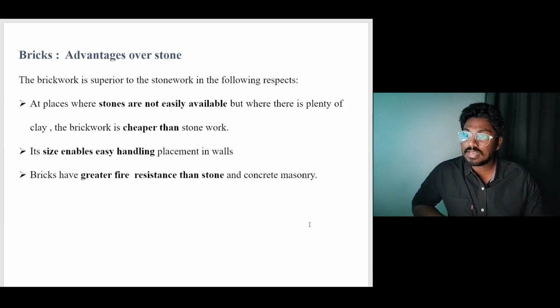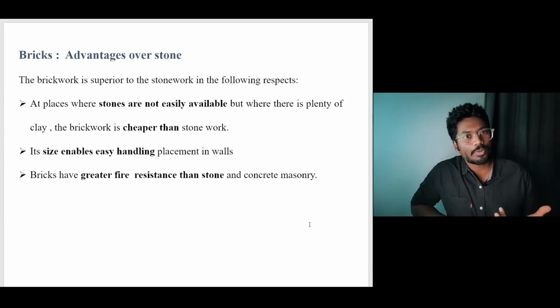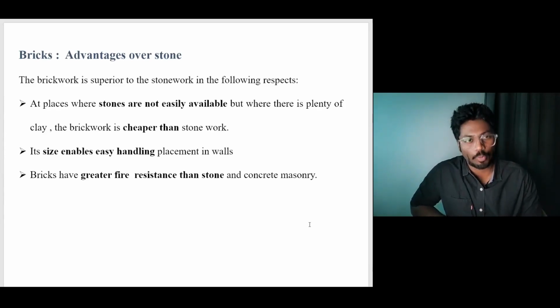Next, the size enables ease of handling. Yes, stones cannot be pruned to a size that is easy to handle. Even if it's trimmed to the size of a brick, it is really heavy and the handling is quite difficult in terms of weight. Whereas brick, on the other hand, even if it's larger in size, you'll be able to handle the weight of a brick compared to that of stone, because bricks are lighter in weight.